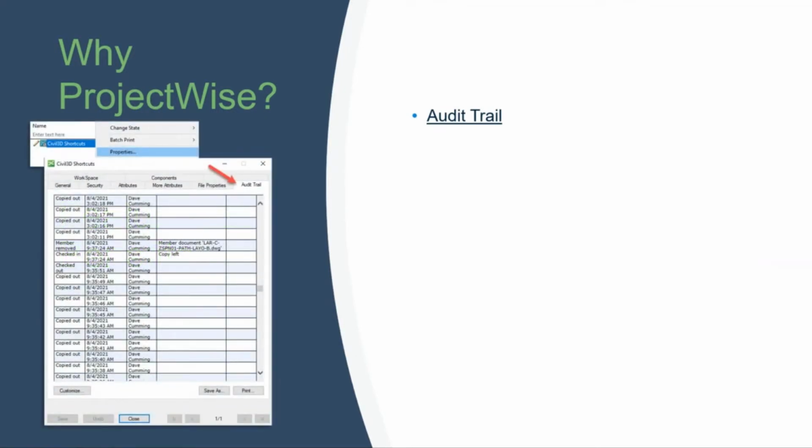So the audit trail, real simple, right? And I do a lot of troubleshooting work. I get called in to help people fix Civil 3D projects a lot. I use the audit trail all the time. Who did what when? If we can find the root cause of something, we know to what extent it snowballs out into the project. We know who to go to to do some coaching. Audit trail is very valuable.